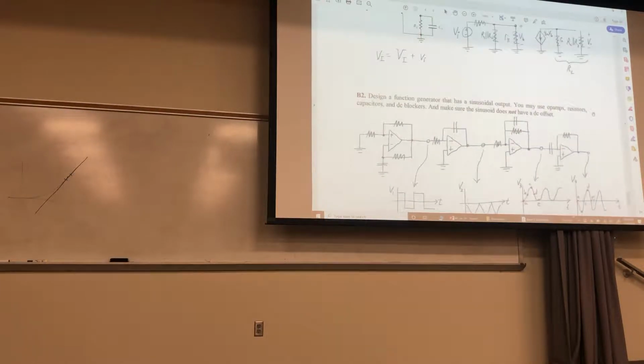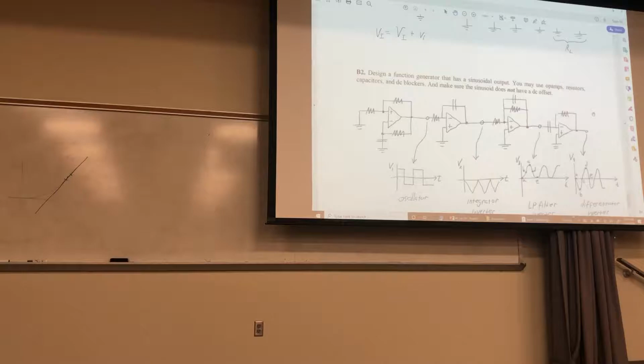Oh, and the reason why this right here is okay for maybe the exam, but it's probably something you want to be very careful about in practice, is because, as we said in class, if you have a noisy signal coming out of here and you differentiate a noisy signal, it's going to look at the slope of all your noise. So if this was like some noisy sinusoid right here, it wouldn't come out as a smooth sinusoid. It would be all over the place. So in practice, you want to maybe filter your signal before going through here, or use another method.